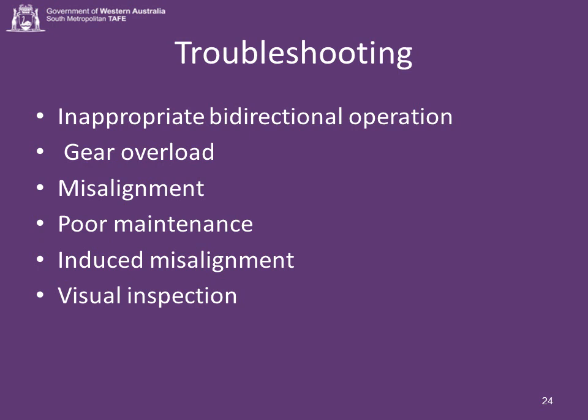Poor maintenance practices are the primary source of real misalignment problems. Proper alignment of gear sets, especially large ones, is not an easy task. Gearbox manufacturers do not provide an easy, positive means to assure that shafts are parallel and that the proper center-to-center distance is maintained.